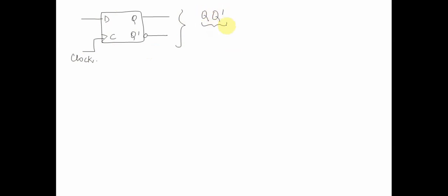Just before we end the lecture, I want to talk to you about one more concept, and that is synchronous or asynchronous inputs. We already saw a D flip flop, which has Q, Q bar. This is Q, this is D, and this is clock. D, clock, Q, Q bar. Now, what if the system is not initialized properly? Can we control the values of Q and Q bar? We don't know what these values would be if we don't specify some input.